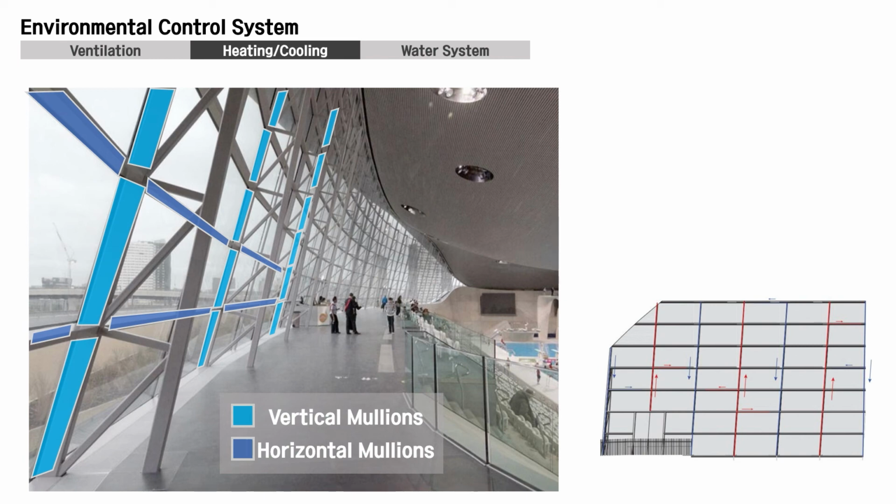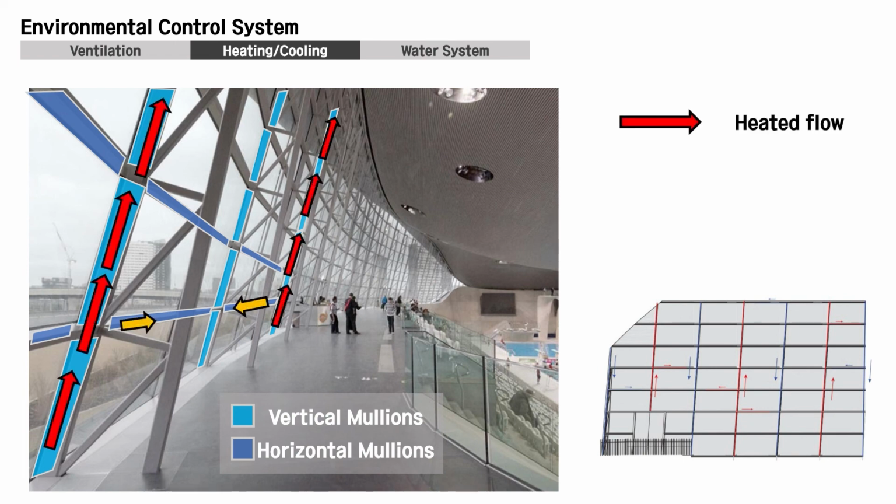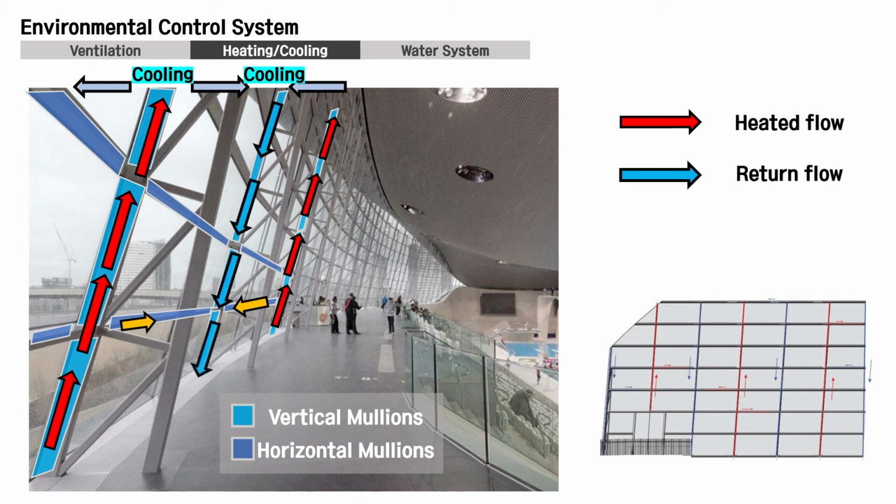It uses pressure to move the water through the tubes, up and down the mullions, and across a few of the larger transoms. The water heats up the air at the base of the curtain wall, which then rises until it reaches the top of the wall, where it begins to cool and descend softly back into the interior. This non-stop movement of air also helps to solve the condensation problem.